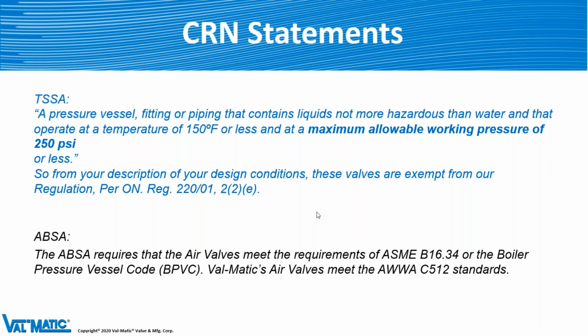But according to the TSSA, this is what they told us about 2 months ago, a pressure vessel, fitting, or piping that contains liquids not more hazardous than water, and that operate at a temperature of 150 degrees Fahrenheit or less, and at a maximum allowable pressure of 250 psi or less.